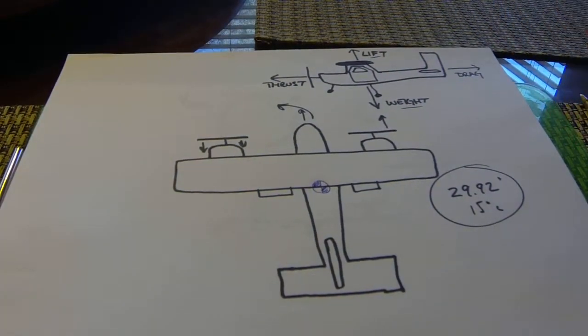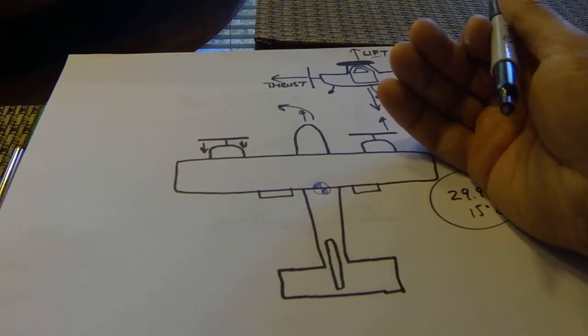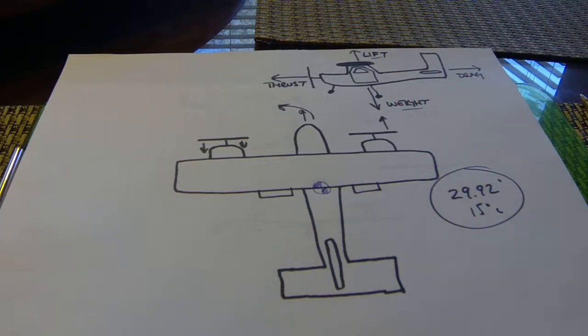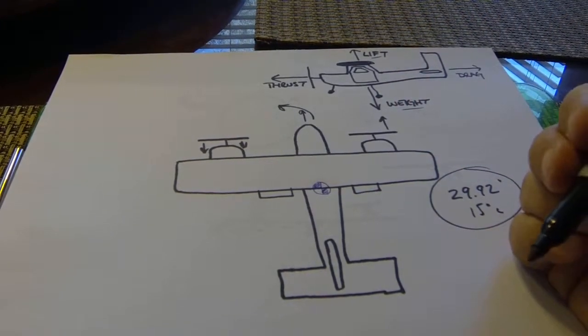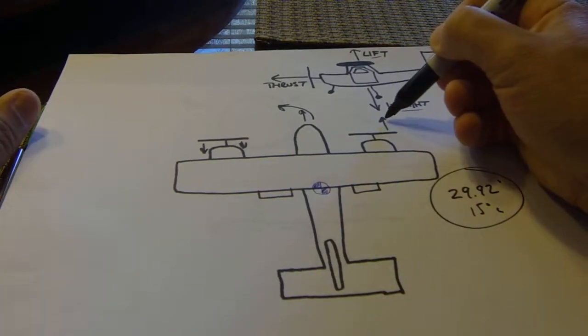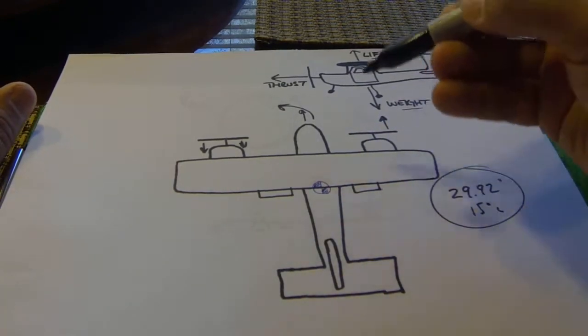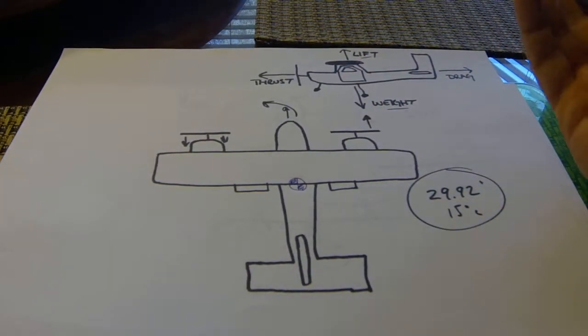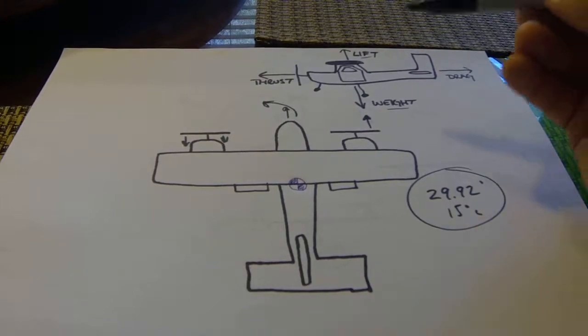Okay, if we put the flaps up, VMC is going to increase. Obviously, if we put the flaps down, VMC is decreasing. If you think about it, we have this thrust vector over here. We put flaps down on both sides because obviously we can't do just one side, right? I mean, if we could, that would be great.